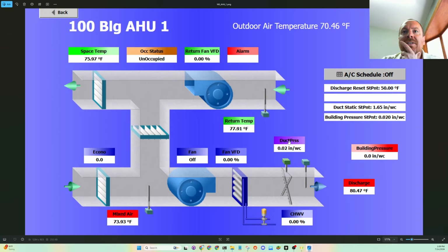If we were doing Guideline 36, we would be resetting the duct static pressure based on demand, which would come from zone level input from VAV boxes, and resetting the leaving air temperature set point. Yeah, so they're definitely not doing that. And I feel like there's some broken band-aid in the building that needs a deeper dive before we could start doing duct static pressure and temperature resets.